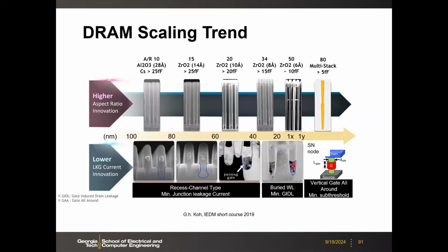Is it fair to say that in the buried style, the L effective reduces? What's your question? Because in buried you're pushing the poly, right? Would the L effective of the channel reduce so the leakage will increase? No, the channel is still like this, right? It's just burying the word line down to here. Okay. You replace that with some metal or gates instead of poly gates.